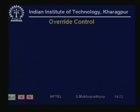Coming to override control. In override control, the same system could be operated based on two different modes or philosophies. Basically it is something like an if-then-else logic: as long as this is happening, operate the system in this way, but if that happens, operate it that way.